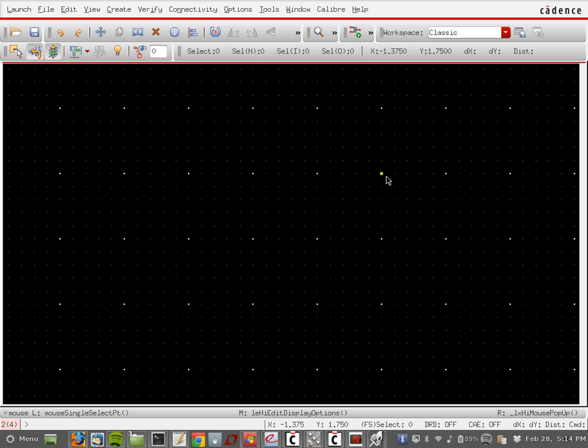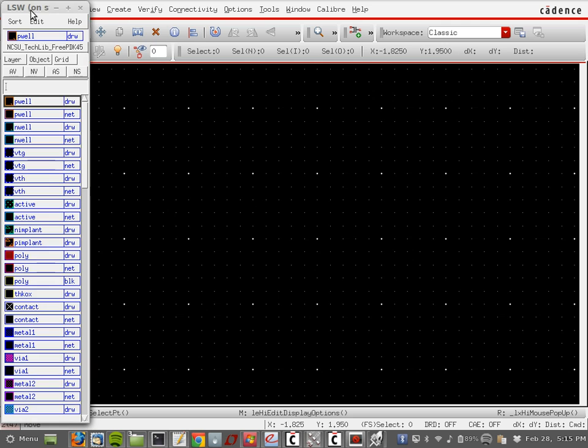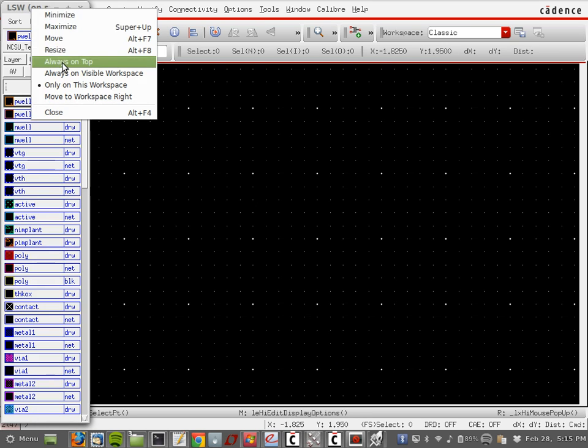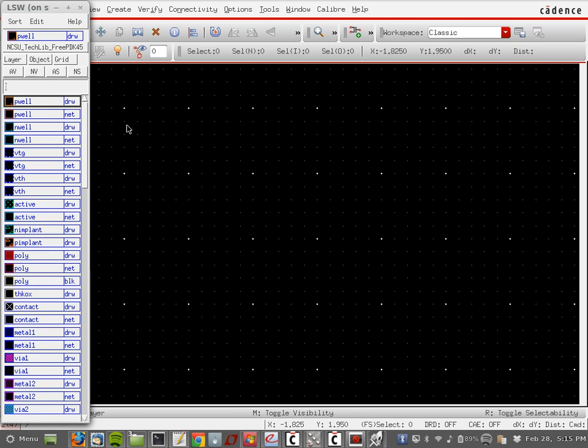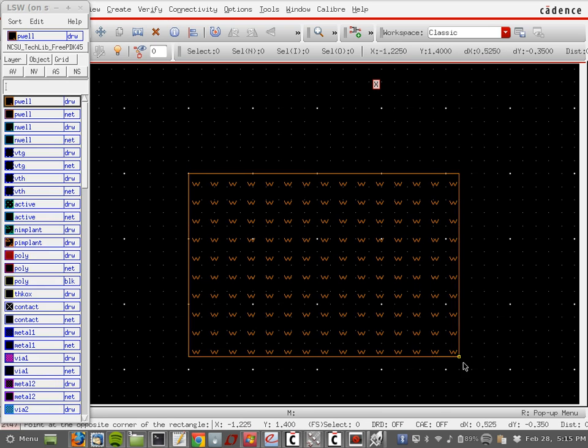Okay, so how many dots should I make for my channel? Remember, it was two lambdas. So 2 dots would be the length of my channel here. But let me start again with the P-well. I'm not going to pay much attention to dimensions now. I can optimize it later.